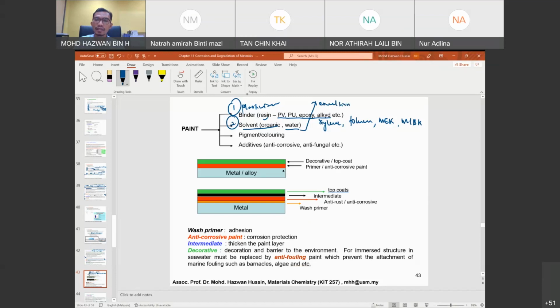Siapa tahu emulsion paint ni kita guna kat mana? So emulsion paint is normally used, this is actually yang cat putih tu lah, that you use to paint your wall. So emulsion paint actually uses water only. Okay, water and maybe titanium oxide as the main ingredient. Okay, and then you will have pigments or coloring. You have a pigmentation agent like, as I said, titanium oxide. Coloring, maybe you have a different color, Congo red, color whatsoever, and then you have additives.